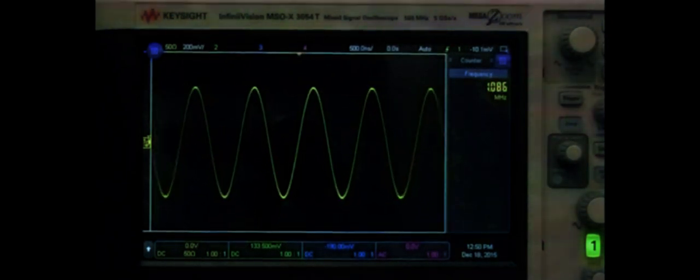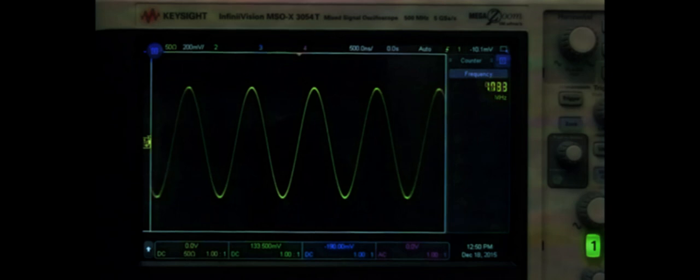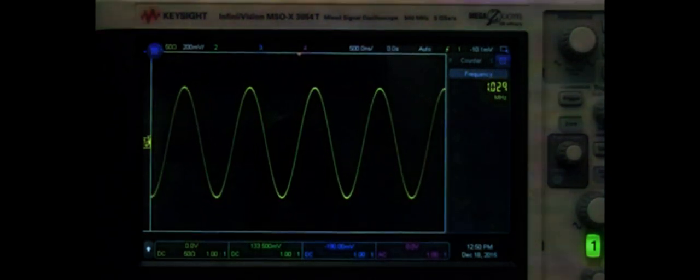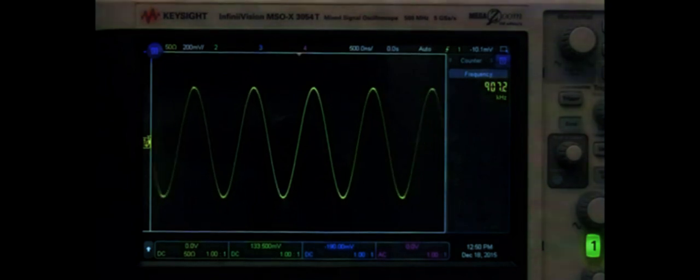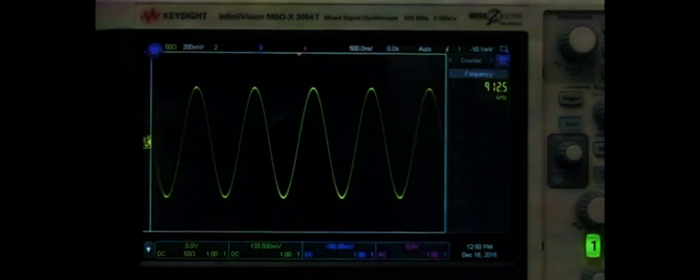Now this is what a frequency modulated waveform looks like. The amplitude stays the same, but we're changing the frequency. In this example, the carrier wave is 1 MHz, but we're slowly changing the frequency, so it's transitioning between 0.9 MHz and 1.1 MHz. We're doing the modulation here at 1 Hz, so it's nice and easy to see. And this is what it looks like at a more realistic frequency of 1 kHz.